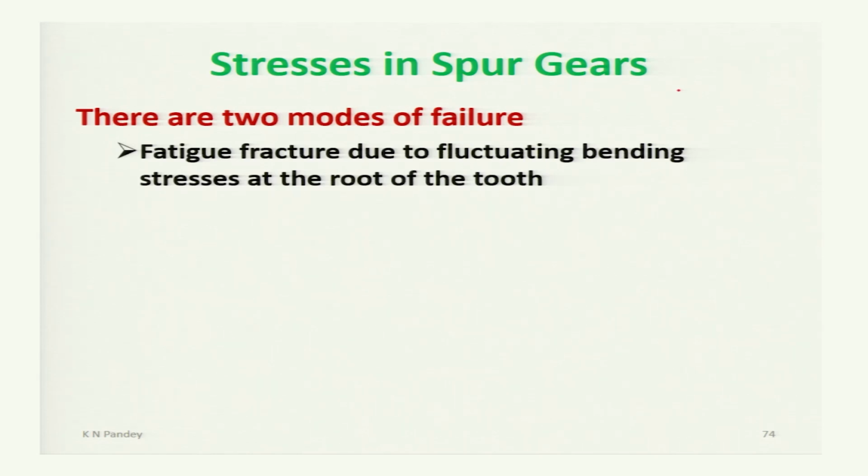That means we have found that this is a gear tooth, then the load which acts along line of action is this F32 or 23, whatever we may say. So let F32 is the force which is acting along the line of action. Now it has two components, the transmitted load Wt and the radial load Wr. Okay, so this you may say is equal to W. Now here it is like this.